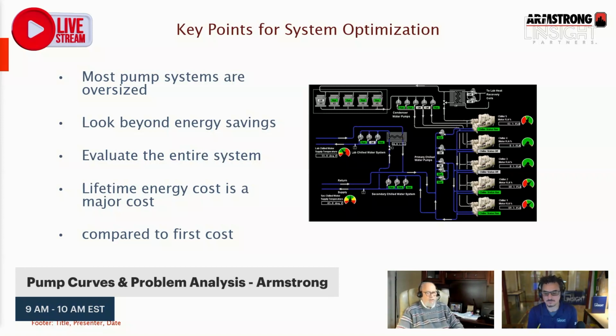You know, they tested." And I'm looking at what they tested, and they tested at different speeds than what the pump was designed for. And I'm going, guys, you tested it at the wrong speed. Reduce your speed to here, which is what the maximum speed for this pump was, and retest your shut off head. And they come back and go, "Oh, wow, you were right. We were wrong." And I go, "Okay."